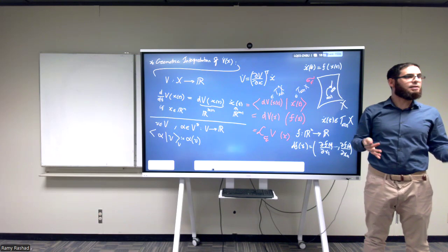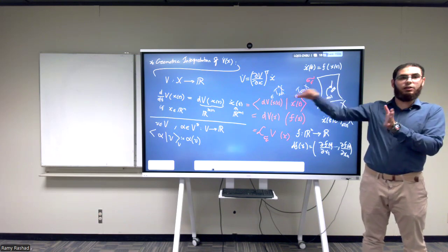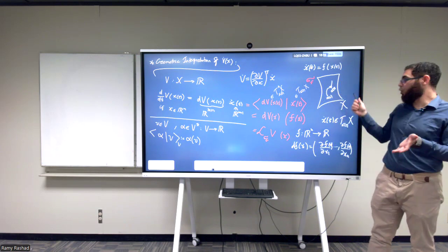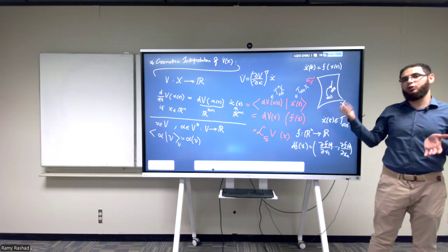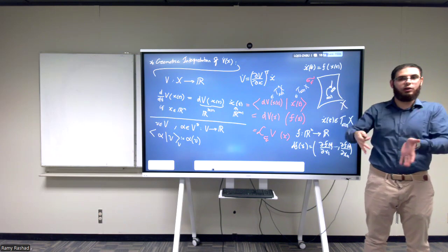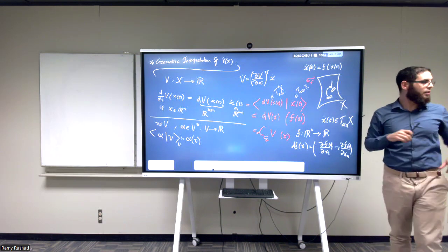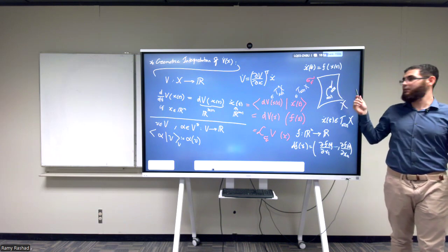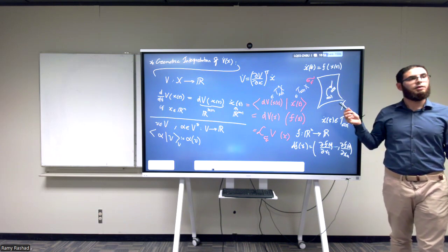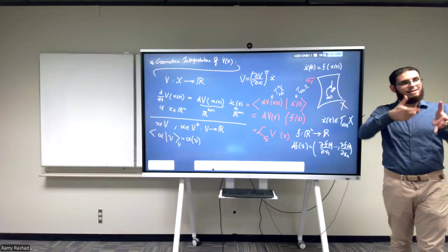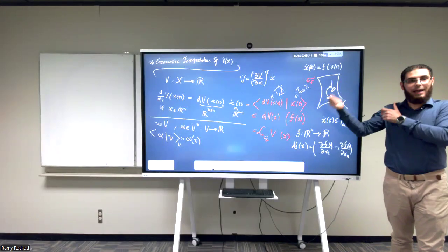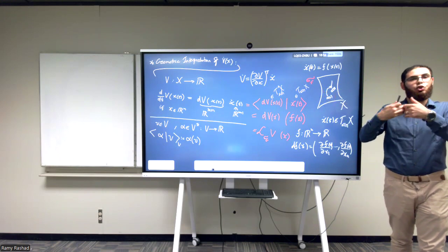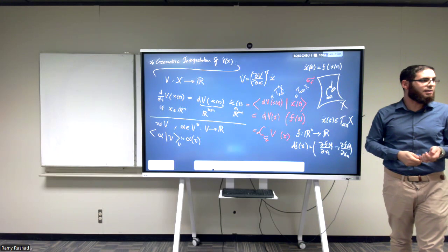Of course, in practice, usually we're not going to see all of that unless you have a very complicated example, because usually we work in charts. When we go to the case of SO3, we don't use charts, right? So we have to work on SO3 directly, and this is why this is going to be very important. Later on, I'm going to even show you, I hope we're going to have the time to do it, even on SE3. To develop a controller on SE3 that you can actually implement directly. Implement a geometrically nonlinear controller on SE3 directly.